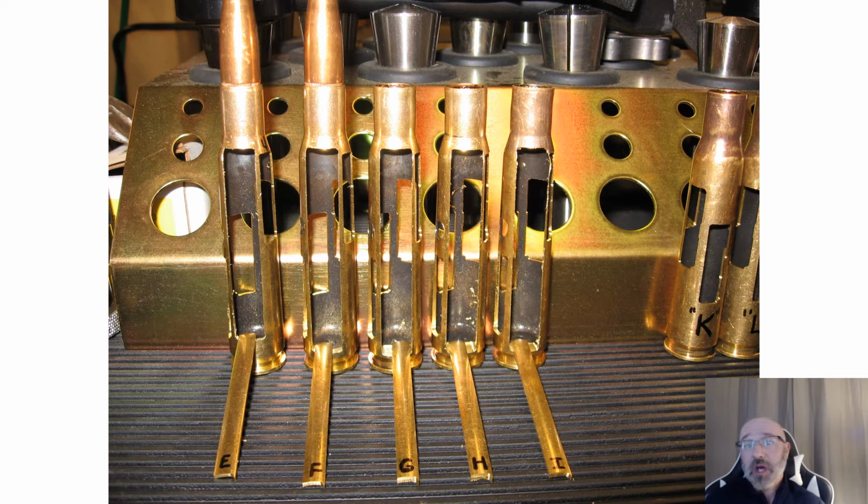We talked about this with the different types of manufacturers before in the design process, where there are different levels of control that you can have over the machining and manufacturing process. This one we had a lot of control over, and we could actually be in the machine shop as they were being machined, double check, and make sure the specimens were the right size and everything was correct. This is important for us to, one, get our machining speeds down. We didn't want to work harden any of the parts, so we used the correct lubrication, got the correct sizes and dimensions, and made sure we could get the most test specimens out of these.